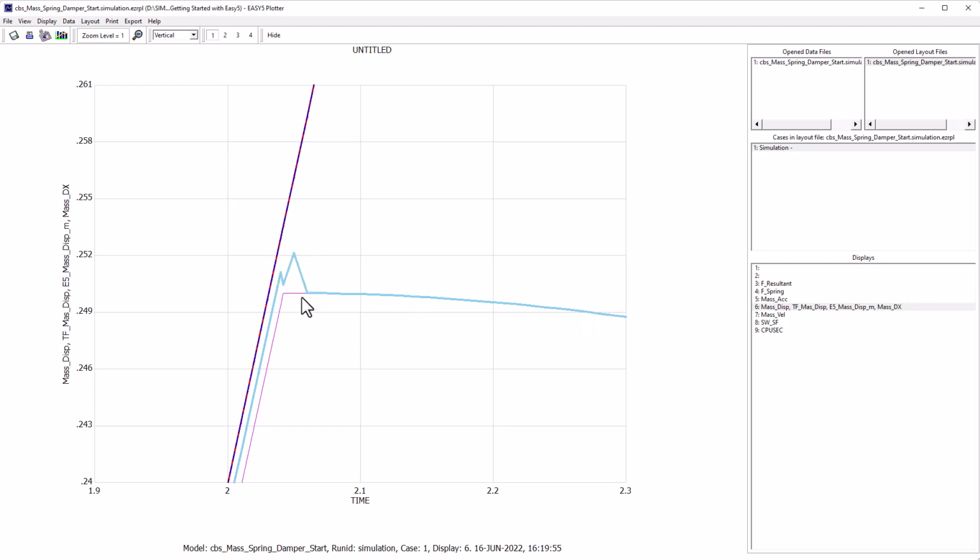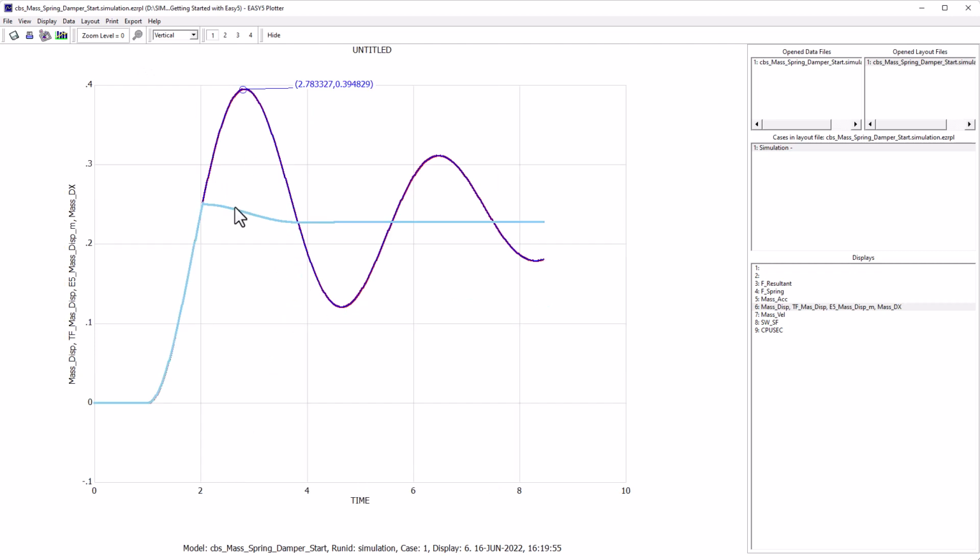And so this just shows you that in an Adams model, you can play around with the stiffness and the damping and the penetration factor that's allowed in terms of triggering contact in Adams. The more you try and approximate this, the more the Adams solver is going to battle because you are approaching a numerical discontinuity. But again, here you can see that once the contact event has taken place, Adams and Easy5 almost behave exactly the same.